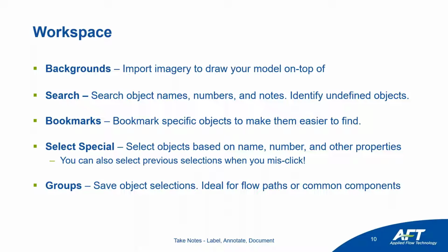So say that we go through all of this work to create a selection. How can we save that selection to use it again in the future? If I'm doing massive pipe changes, maybe I have 100 pipes and I'm testing them at 5 inches, 6 inches, 8 inches, I don't want to constantly be reselecting and re-identifying those pipes, right? So groups let us save those selections so that we can use them again in the future.